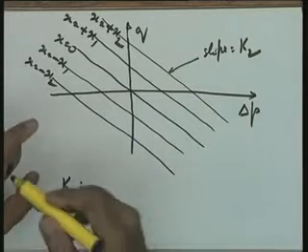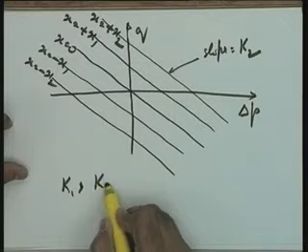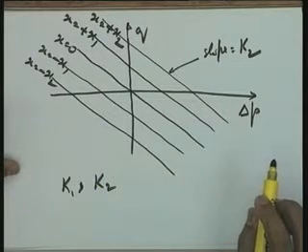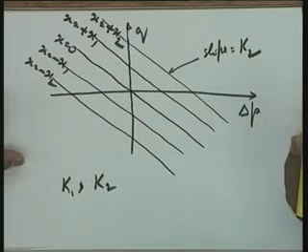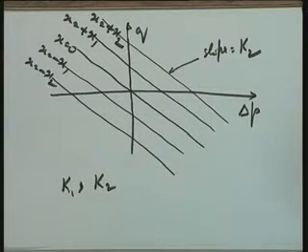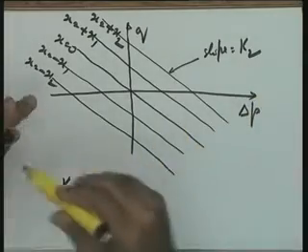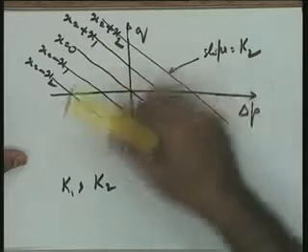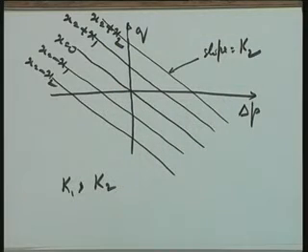K1 and K2 are the two parameters of this particular model, and I am going to use the relationship that the flow Q is equal to K1x minus K2 del P, where K1 and K2, I re-emphasize this point, are normally obtained from experimental data supplied by the manufacturer. You simply fit your steady state point on that data, linearized around that steady state point, and get the values of K1 and K2 from that information.